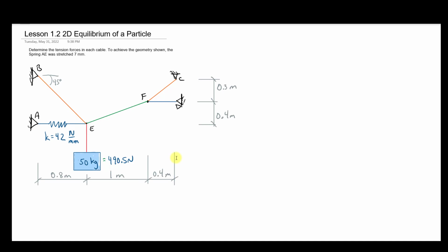And to draw a free body diagram, I state it with 3 simple rules. Once you've identified what you want to draw a free body diagram of, you do 3 things. One is you keep the part that you're keeping. So you figure out what you're going to cut, and then you keep the part that you're keeping. Step 1. It sounds very obvious, but you follow these steps precisely and they give you profound answers. Okay, so step 1, keep the part that you're keeping. Draw the diagram with all the parts you're keeping, all the geometry, all the angles in this case. In equilibrium of a particle, I need to see all the angles on my free body.